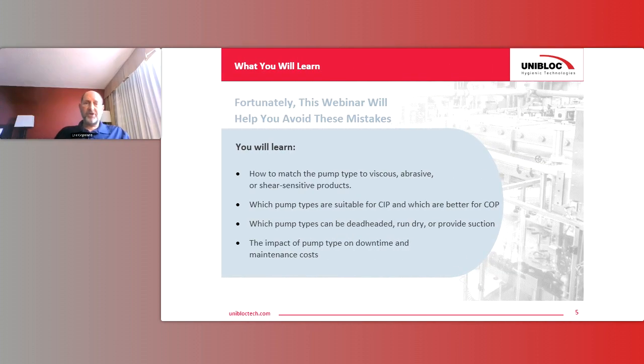So some of the things we hope you'll learn today is how to match a pump to the right product you're pumping from a viscosity standpoint, from an abrasive standpoint, from a shear-sensitive standpoint. Which pump technologies are best suited for CIP versus COP. So obviously CIP is clean in place, COP is clean out of place. Not all pump technologies are equal when it comes to how you plan to clean the pump. If there's occasions where the pump can run dry, again, certain technologies are better at dry running than other technologies in the pump industry. So you want to choose the right one.